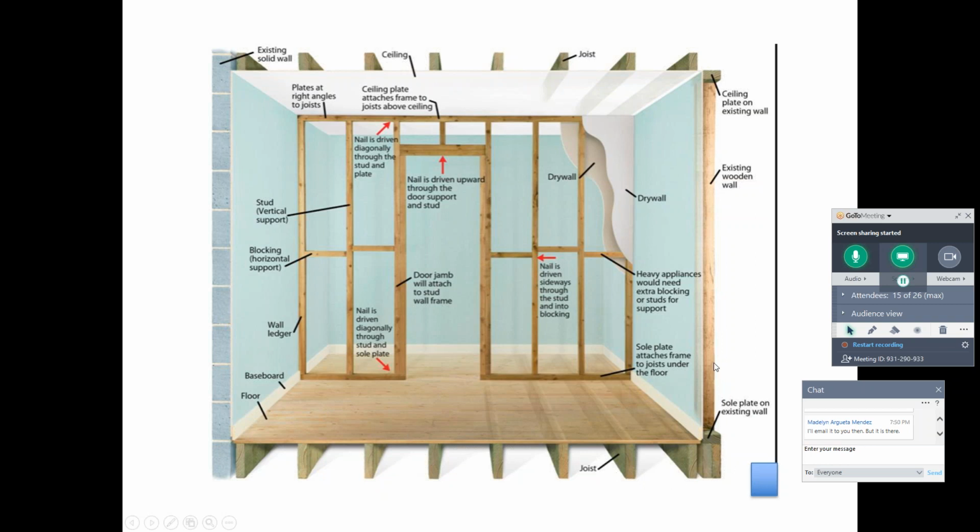So the exterior, we'd have studs, and then atop our studs, we would have some thickness of drywall. And then going towards the outside, we'd probably have a layer of insulation between these studs, and then possibly we would have a protective layer and then our siding. And then at the top, we simply have drywall, more joists, depending on how many floors we have above, or this could be the plenum in which we might have joists at a different spacing with an attic above and kind of a truss. And then here it's showing a concrete wall, so who knows what this goes to.